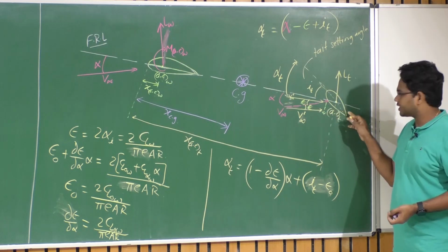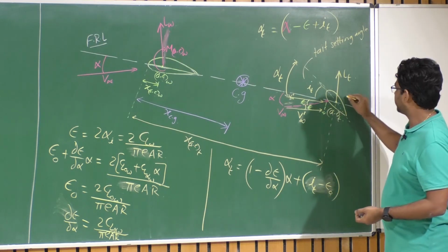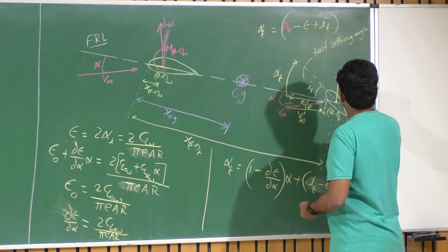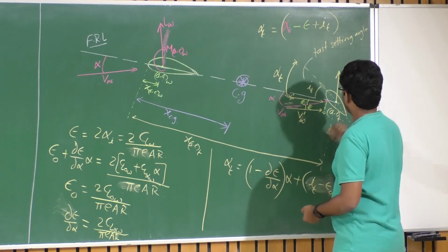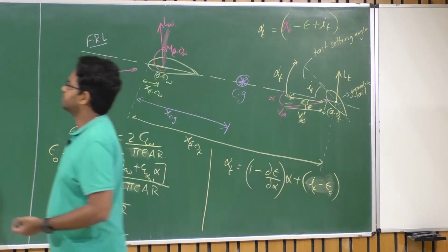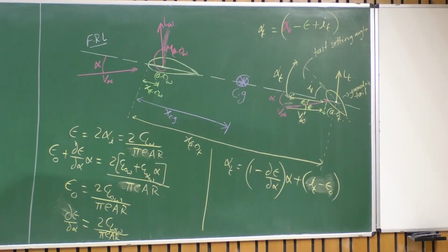Do I have a pitching moment coefficient or moment about aerodynamic center? Why? Because we are using a symmetric tail, right? In general, it is a symmetric tail, right? So made out of symmetric aerofoil. So we don't have CMAC there.